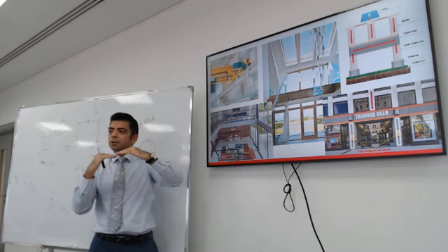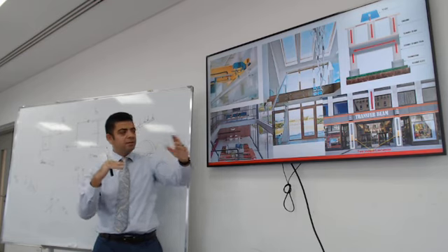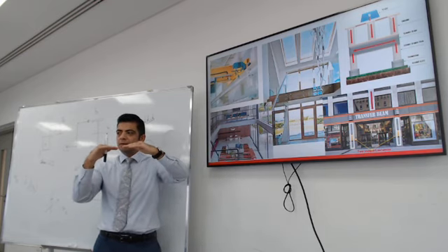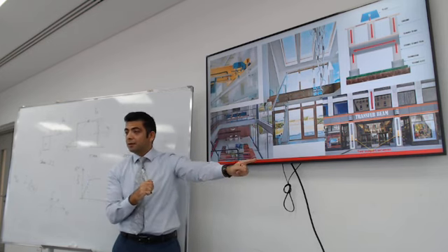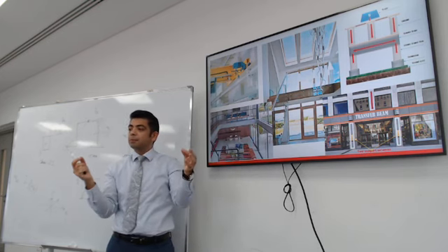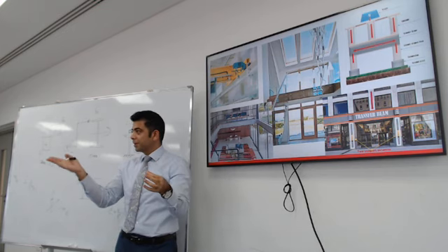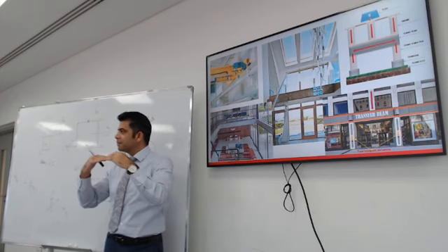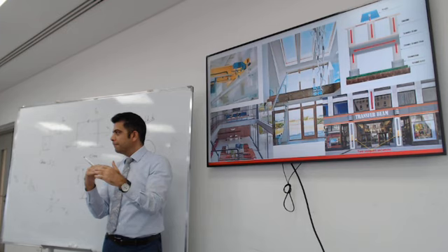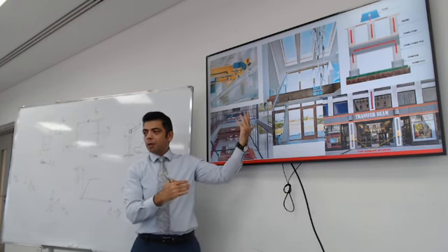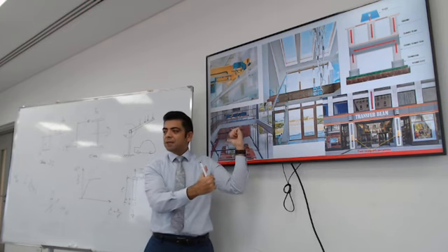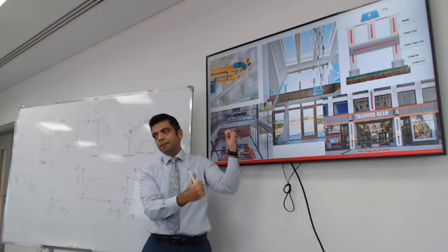So what is preventing this beam from moving sideways? There is another column the other way. Yes, so it's restrained at the beginning and at the end. What about the entire length of the beam? It looks like it's unrestrained. Why did you say that? Why is it laterally unrestrained? Nothing is stopping it. When the wind hits that window, it's going to move that beam sideways. Nothing is stopping it from moving.